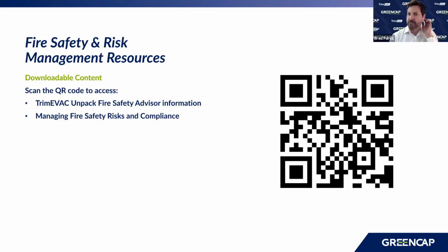Yep, I'll get that one. No, exit doors themselves need those, but you're also obliged to provide directional signage so that someone actually knows how to get to the final exit. So that will often mean that doorways on the path of travel from where you happen to be in the building to the final exits should have illuminated exit signage over them, so you can actually wayfind to that final exit.